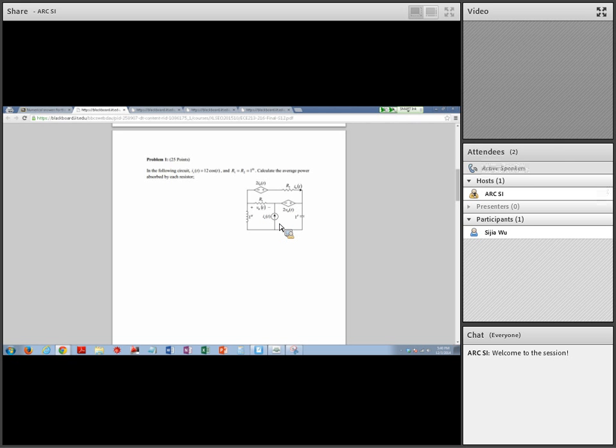Do you guys see anything? Any trickiness? Seems pretty straightforward. The only constraint equation, if you use mesh, would be that current source, right? Like nothing with the voltage sources. No. Yeah, it doesn't look too bad.